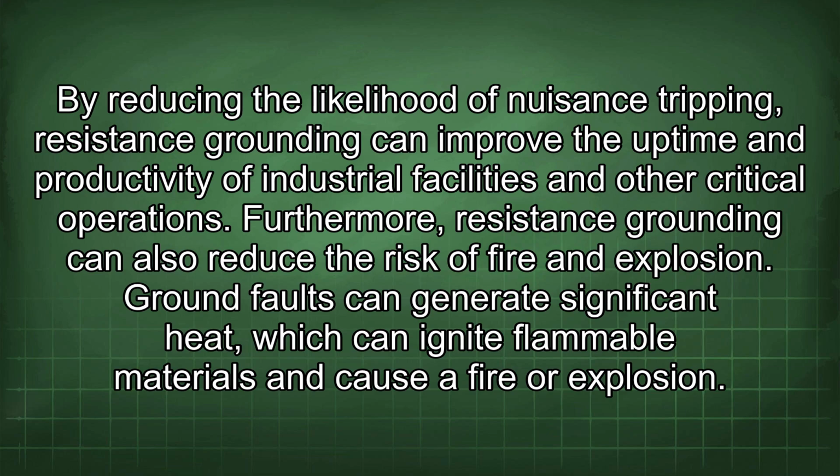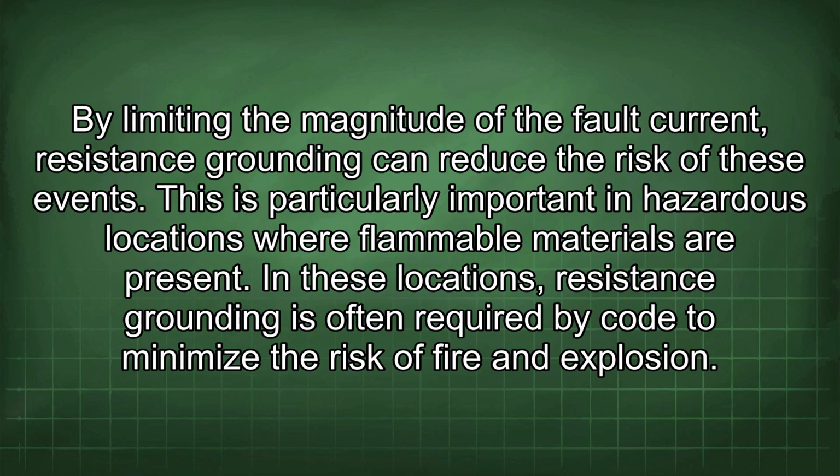Furthermore, resistance grounding can also reduce the risk of fire and explosion. Ground faults can generate significant heat, which can ignite flammable materials and cause a fire or explosion. By limiting the magnitude of the fault current, resistance grounding can reduce the risk of these events. This is particularly important in hazardous locations where flammable materials are present. In these locations, resistance grounding is often required by code to minimize the risk of fire and explosion.